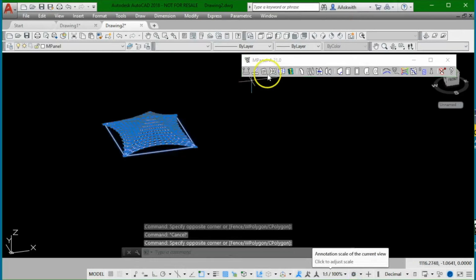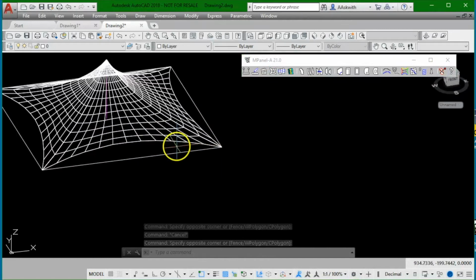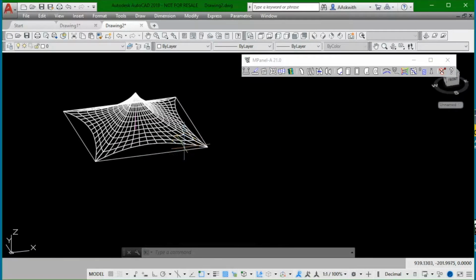and we'll now get a pole tent which is perhaps more the kind of shape which you might be used to designing. Just making it clear that the cables which run down the hips here may actually be webbing, or they may actually be just the stiffness of a lace line, or the stiffness of multiple layers of fabric sewn or welded together along those hips.